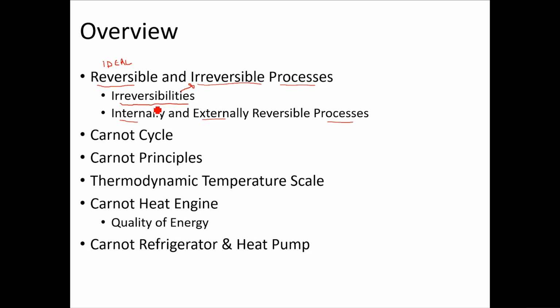Internally reversible processes are processes in which the system would come back to its original state after completing a process. If you perform a certain process on a system, and the system is able to get back to its initial condition, so there are no irreversibilities present within the system, then it's an internally reversible process. If there are no irreversibilities present in the system and the surroundings as well, that's an externally reversible process, but we'll look into them in detail.